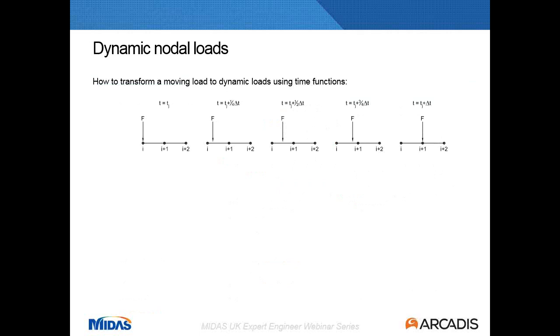Right, so we have these train models, and the question now is how we can introduce these train models to the dynamic analysis. Well, these load models will be basically axles moving on top of your bridge. And here I have an example of one axle load. This is this load over here that is on top of one of the nodes on your bridge, assuming that you have modeled that as a beam element, but it's the same thing for any other element.